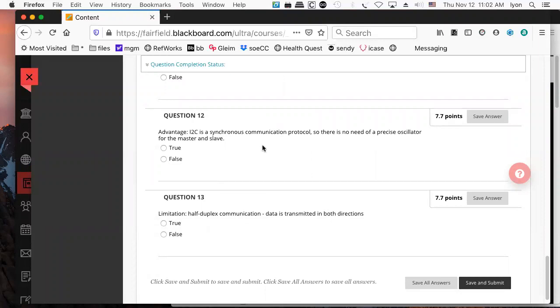Right. Okay. So we have one clock line and we have one data line, and we're sharing the data line just the way we did in the lab yesterday. We were sharing the channel with all the NRF24L01 transceivers. So when people started to broadcast at the same time, we stepped on each other's packets. When you have a media access control layer, what you do is you sense the carrier of somebody who's already transmitting, and you wait for them to finish, you see.